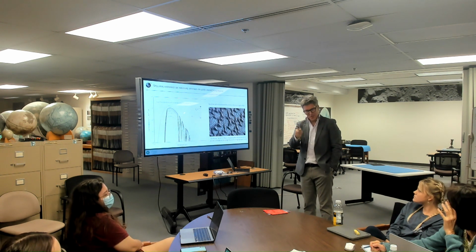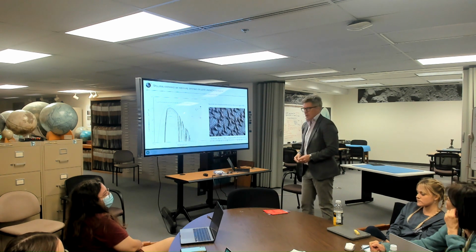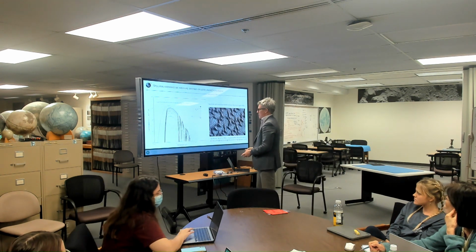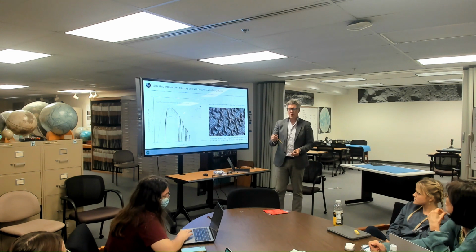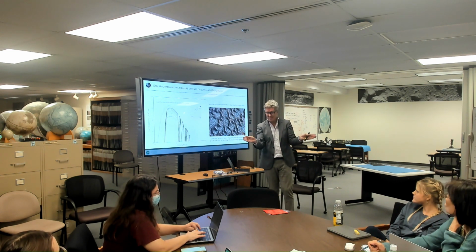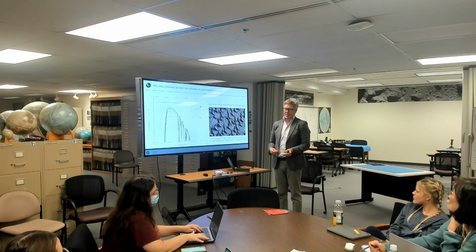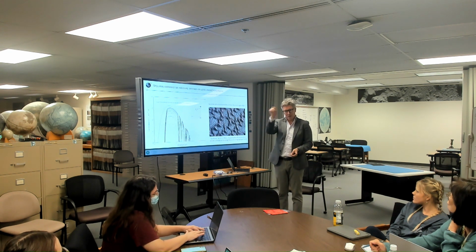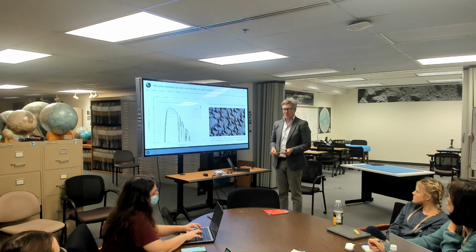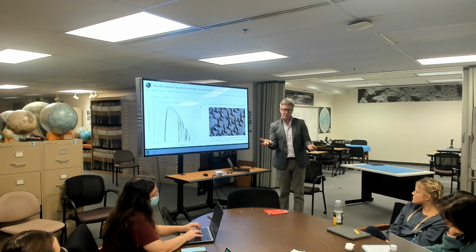If the sun and the satellite are at different points in the sky, right? So when people design orbits to do reflectance spectroscopy, they try and make sure you can't have the sun and the satellite at the same angle all the time, right? Because stuff's moving. But on the Earth, for example, the Landsat spacecraft I showed you with those orbits in that movie is in what they call a sun-synchronous orbit, which just means that the orbital plane precesses around the Earth at the same rate that the Earth rotates, about a degree per day, right?